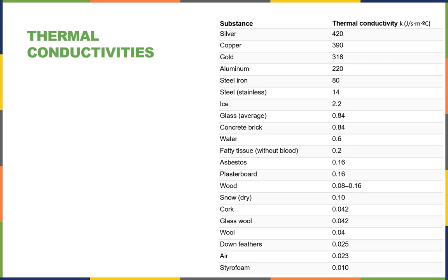Right now, all we've talked about is thermal conduction. That air is very poor at thermal conductivity, and so you have very poor conduction through. Polystyrene must also be pretty poor, but you also have to think about that polystyrene. It's very thin channels of polystyrene with air bubbles in between. And so the area is small, which slows down the rate of conduction through the polystyrene. And the length is pretty long, which also slows it down. So styrofoam is a really good insulator, primarily because it's a bunch of trapped air bubbles.